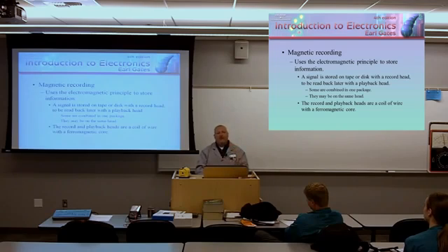That pattern will be stored on that tape, but not indefinitely, because if it's stored here on planet Earth, what's one of the things it could be under the influence of? The Earth's magnetic field. If you put it in close proximity to any other electromagnetic device, it could alter that. So magnetic recordings will not last forever. As a matter of fact, every time you play a magnetic recording back and read that fluctuation in the particles, it loses a little bit of what it was originally.